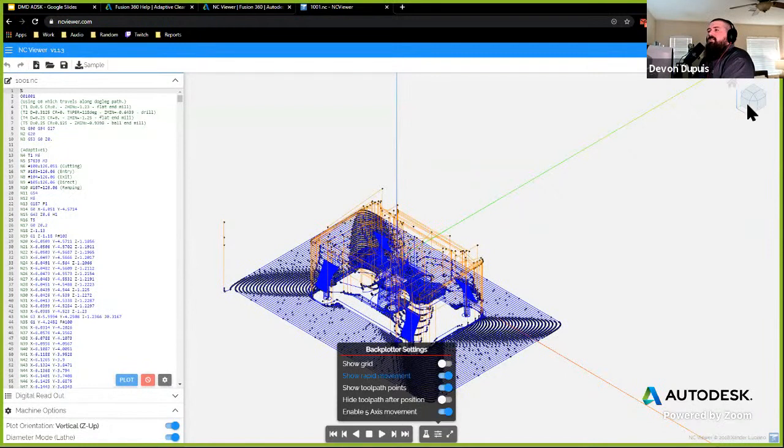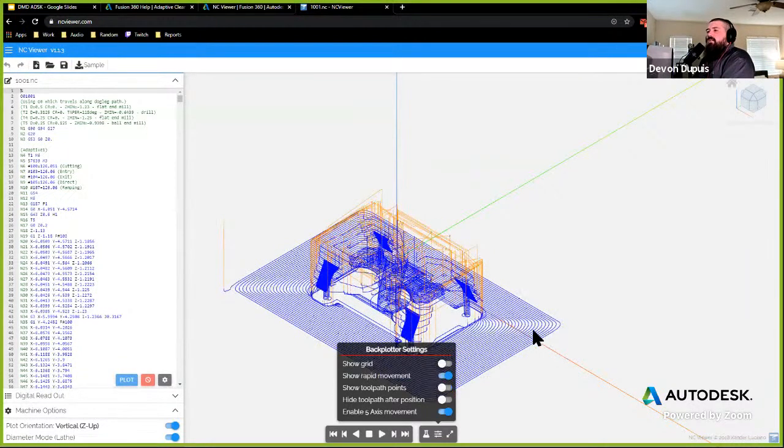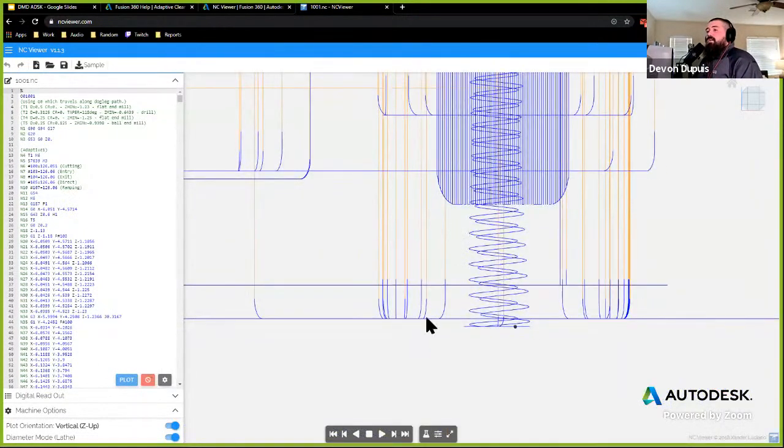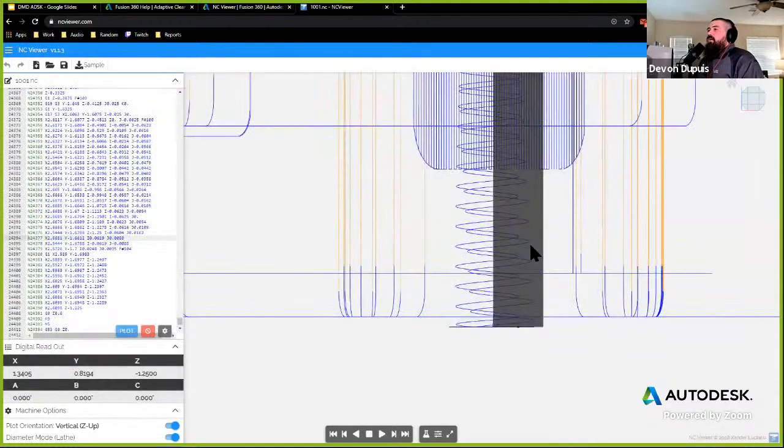And the nice thing is maybe I want to go to this front view and click on part of this bore toolpath, click on it. It's going to take me in the program where that comes from, and that might not be super useful, but what I like to see is the digital readout. So this will show me essentially how deep it's supposed to be from my setup. So I can see it's going -1¼ inches there. So that can be pretty useful for identifying maybe how deep something's going to be going at a certain point, or if I have it programmed right, and checking that out.